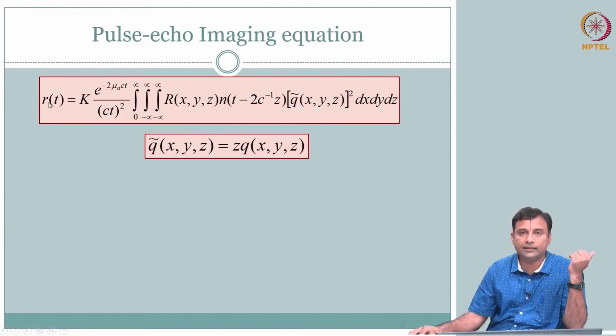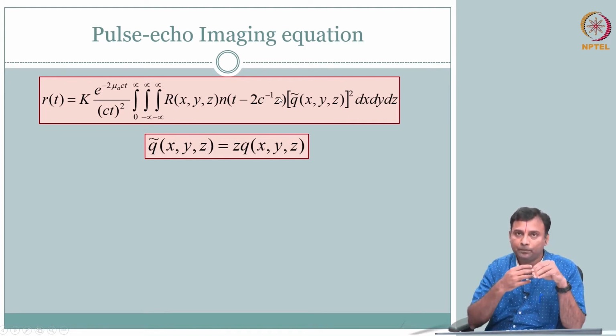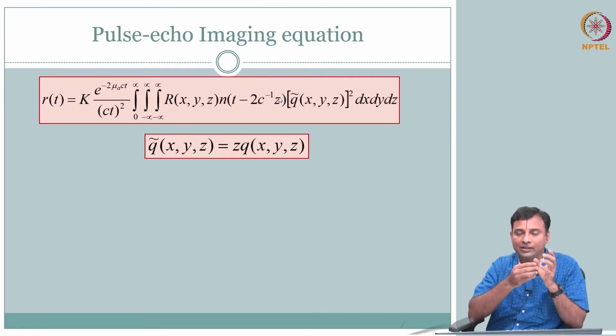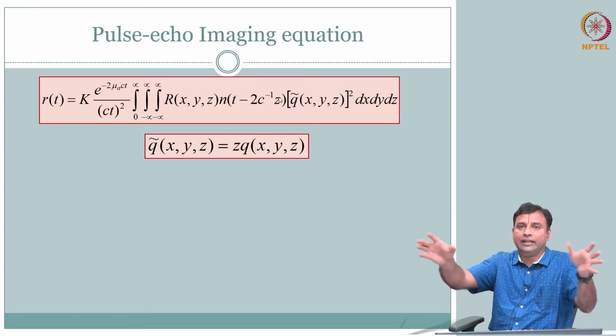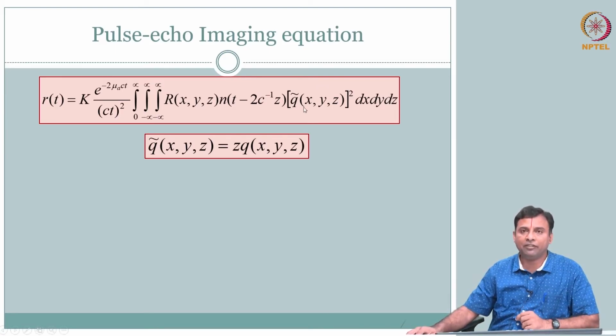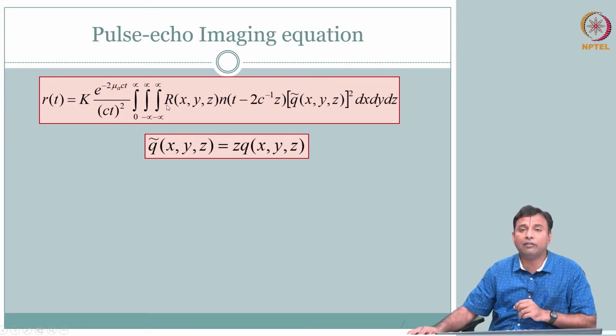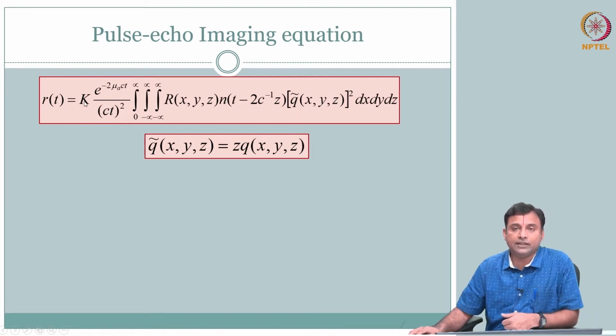So, you send a signal, you get the echoes back, and where the ultrasound wave is hitting after you send it out of the transducer depends on the beam pattern, near field, far field. So, wherever it is hitting, whatever is the reflection coefficient at that location, that amount will come back and you get a net sum. So, at every time point you have a signal, and this is your signal that we talked about. But what is the nature of this signal?